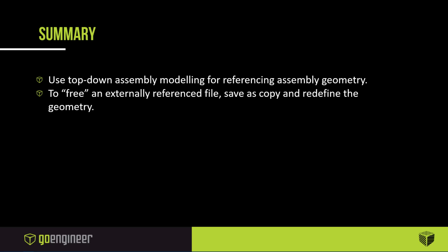And another question here, are there also virtual subassemblies? Yes, there are virtual subassemblies, very much in the same way that you can make virtual parts. As an example, if you have all of your parts in a flat view there in your assembly, you can group them together, make a subassembly that exists just inside the context of that top assembly, but there won't actually be a file that is a subassembly. So yes, virtual subassemblies are a thing.